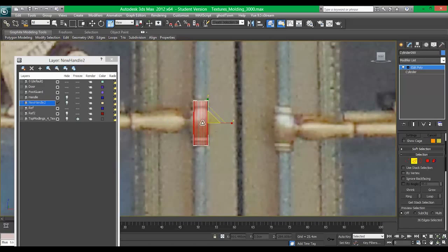Grab the edge tool and make this, I don't know, let's see here, how many are we going to need? We need 1, 2, 3, 4, so let's go with 4 for right now. Then we'll grab our vertices and move them down to where we need them. Move this one down, move this one up, and finally move this one to fit. And we're getting closer here.